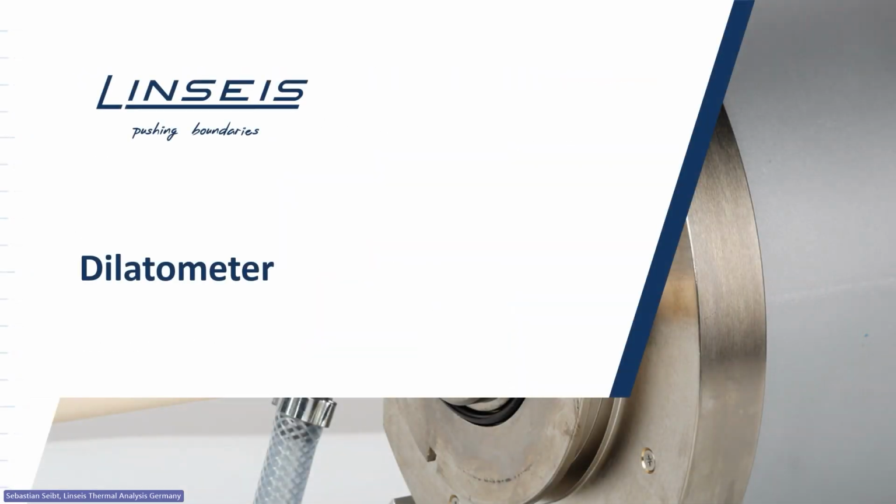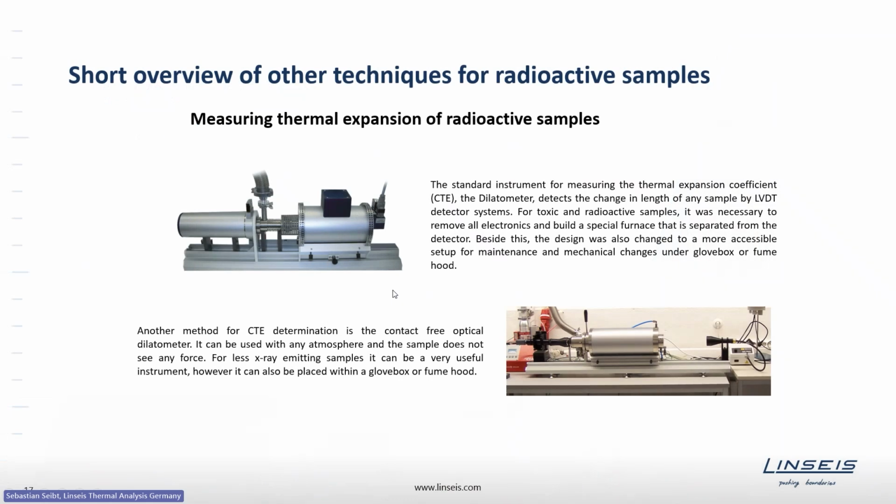The next instrument series that's affected by nuclear applications that we did modify in the past is the dilatometers. Here we have the same concept. For those who do not know what a dilatometer does, usually a dilatometer is used for measuring thermal expansion. It also consists of a furnace chamber. On the picture here, it's the right part.